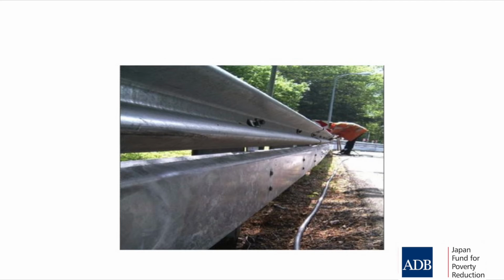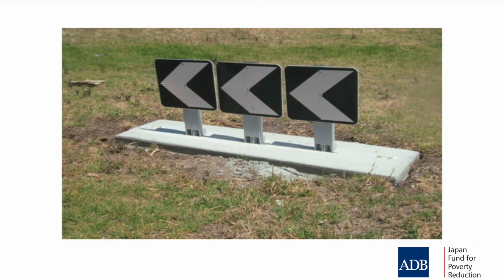They can slide along that as opposed to catching a limb, like a leg or an arm, on one of these posts. That's just one example of many things where the design standard can be improved for motorcycle safety. Another example is signs. We use a very rigid aluminium post. There are signs available that are flexible. So if a rider came off and hit this sign, it would be flexible.